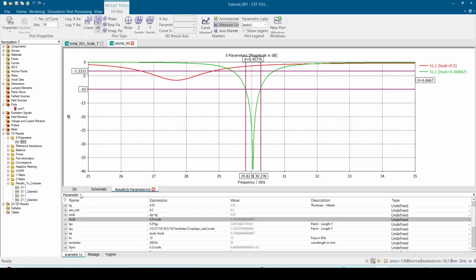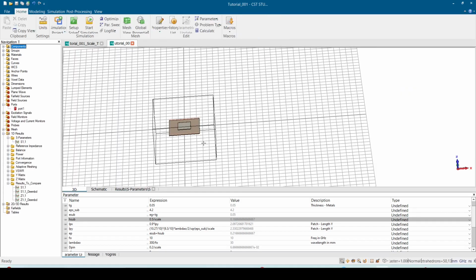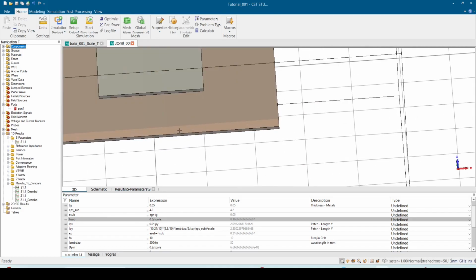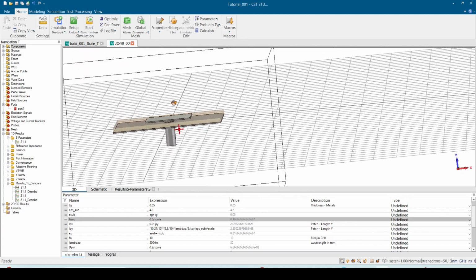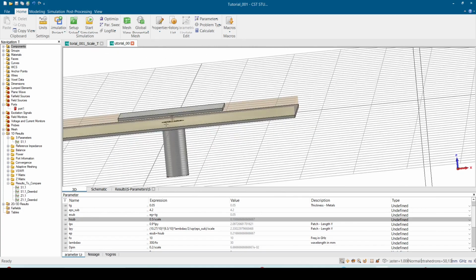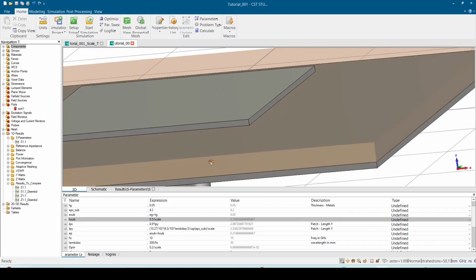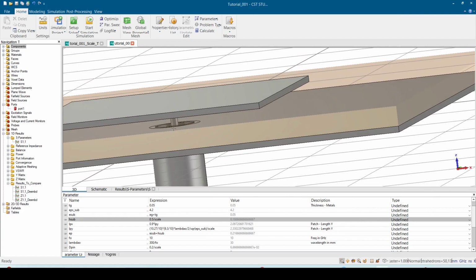So this is generally how we can do it, right? And there are many things we have to consider for successful frequency scaling. First, this is a very optimistic scenario, because when you scale up, if the dimensions are very small, for example, if we want to scale even to higher frequencies, we can reach dimensions of the via or the feeding that are extremely small, not feasible, right?